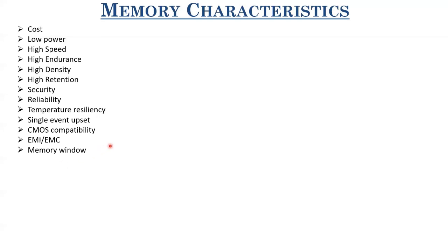Till this point, we are only talking about binary memories, where each memory cell can only store level 0 or level 1. But nowadays, we have several memories which can store more than 1 bit of information. This is known as multi-bit capability. For instance, let's talk about 3D NAND flash memory, which is the prominent storage medium nowadays. In 3D NAND flash memory, each flash cell can store 4 bits of data now.